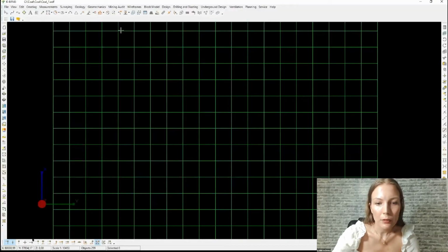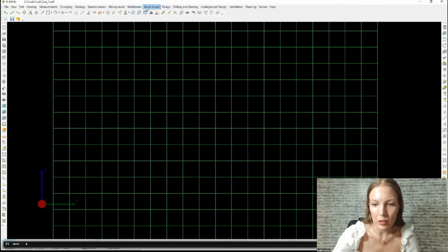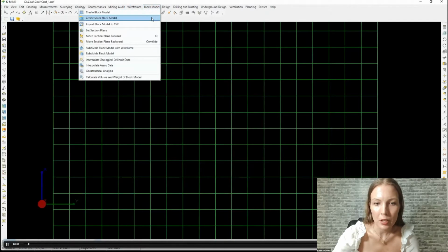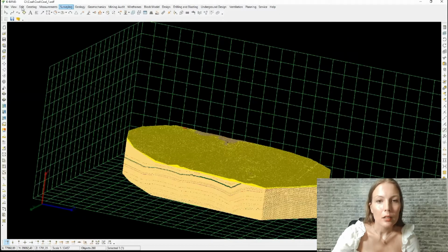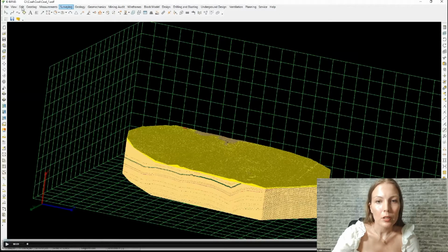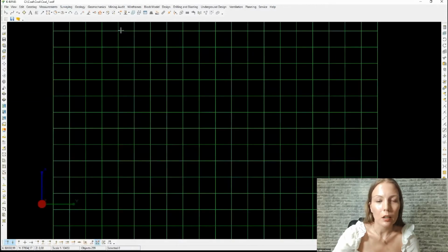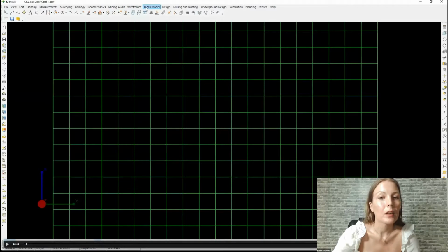So once we define all the layers of the mineral deposit and all of its enclosing rock interlayers, we need to set the marker surface where the seam model will be automatically created. And to create this marker surface, we use intervals of marker horizon intersections in the geological database as source data.